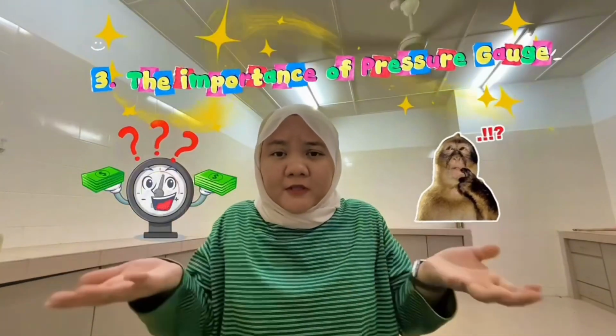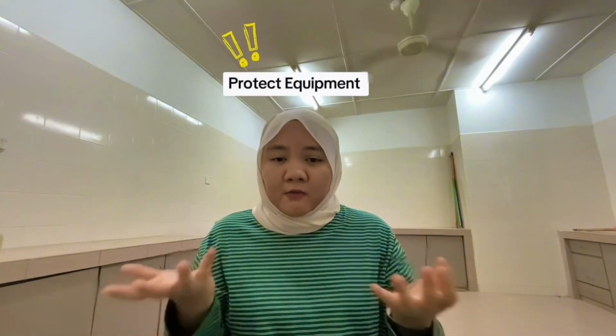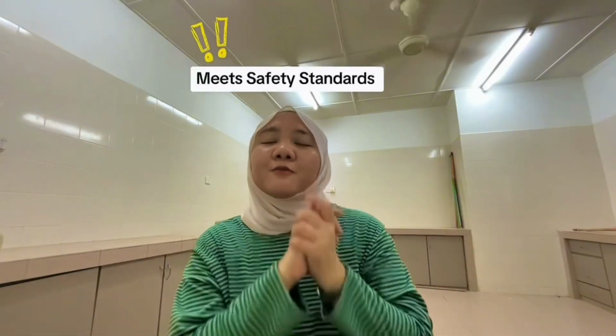So, what is the importance of pressure gauge in the oil and gas industry? A pressure gauge is not only important in the oil and gas industry, but also in other industries. So these are a few reasons why the pressure gauge is very important. The first one is to monitor pressure in pipelines and equipment, to prevent overpressure and accidents, to ensure separation, to detect leaks and other product failures, to protect equipment from damage, to maintain the efficiency of production, and the last one, which is very important, is to meet the safety standards of the oil and gas industry.